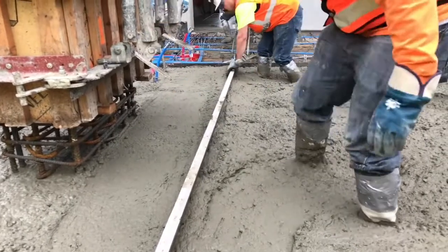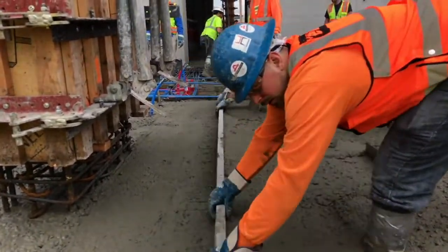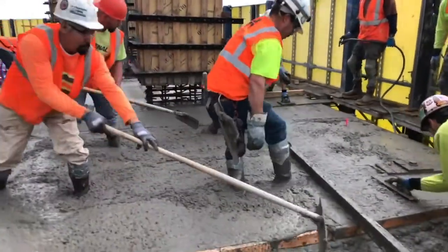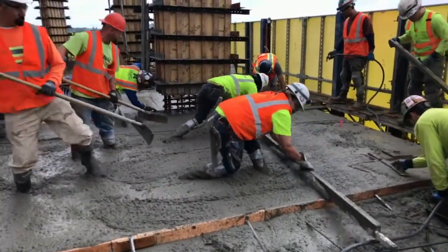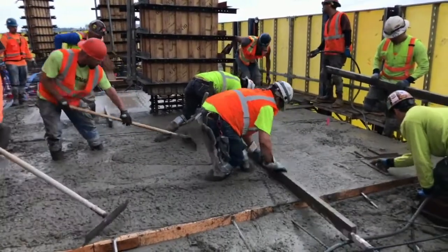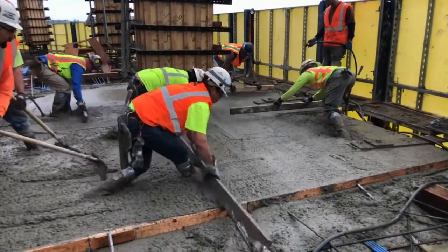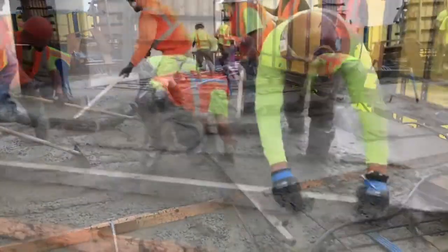From this, reinforced concrete was looked at as it provided increased strength and ductility whilst maintaining low manufacturing costs and environmental impacts. Reinforced concrete uses steel rods placed throughout the column, and these rods are made from steel of a required diameter. My final design used N12 rebar, as anything greater meant that concrete would be taking less load and therefore require a smaller cross-section. Although this is a positive, it again meant that the cross-section would be too small to be plausible.